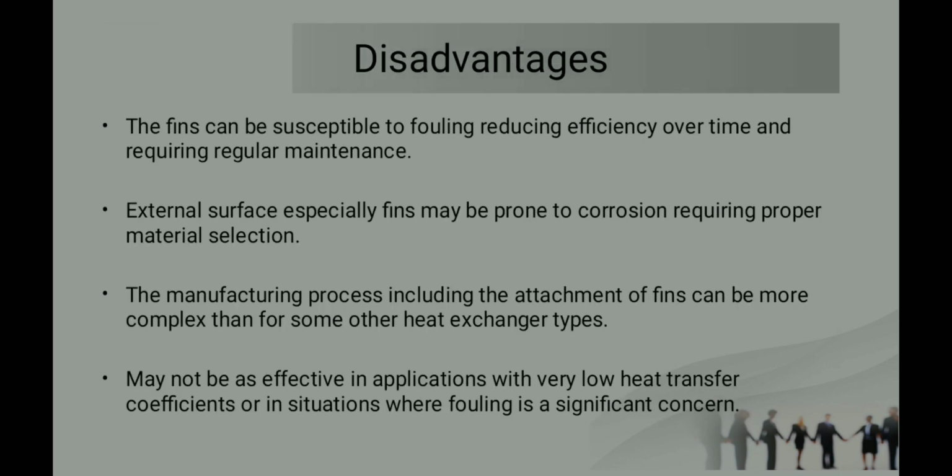Let us look at the disadvantages of a fin tube heat exchanger. The fins can be susceptible to fouling, reducing efficiency over time and requiring regular maintenance. So the fins have a high chance of fouling, which will reduce the efficiency of heat transfer. To prevent that, regular maintenance is required.